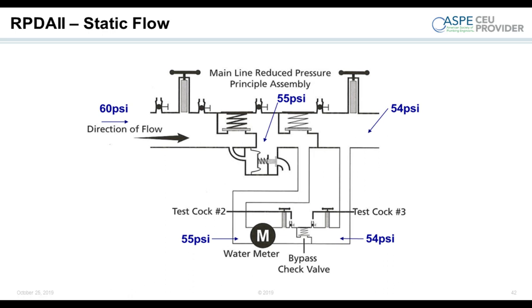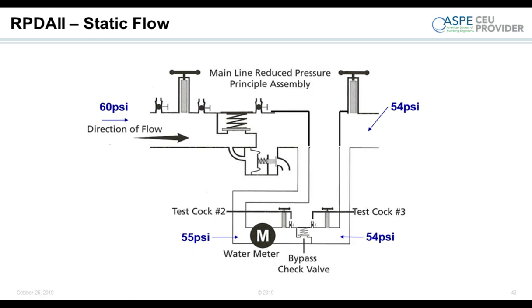So again, we can think of this as 2 different backflow preventers. One backflow preventer that's just the main line, it's all line size. If it's 4-inch, you have 2 4-inch checks. If it's 6-inch, you have 2 6-inch checks. But then when I look at the bypass, we can again think of it just like a backflow that sizes down after the first check. So that reduced pressure zone and your differential pressure relief valve.